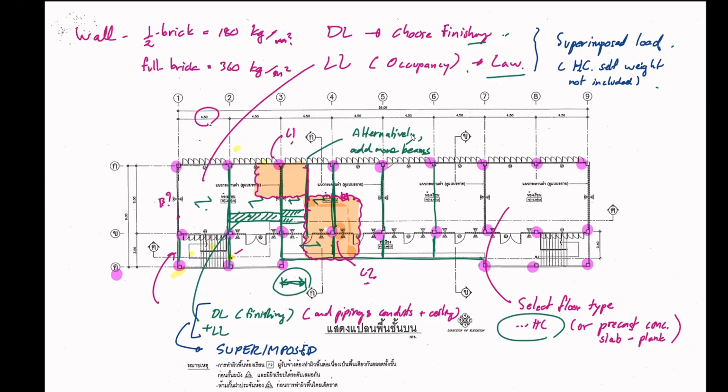Okay. My practice is that I would check all the loads like this and see how different they are. If they turn out not to be so much different, I can use 1 beam section for every beam that you have here. But if they turn out to be so different, I may use 2 sizes, because the load is different and we can save a little bit. But this is going to be part of the frame as well. So if not too much, you may use 1 size for ease of construction. There's nothing wrong with this. Napat, please go ahead.